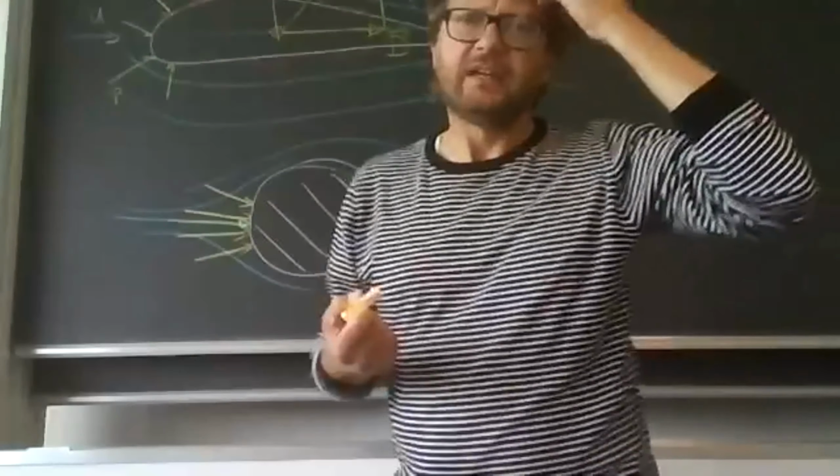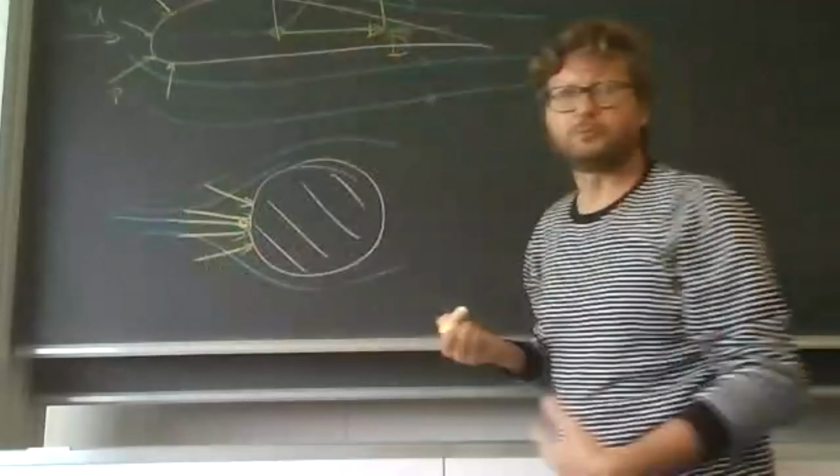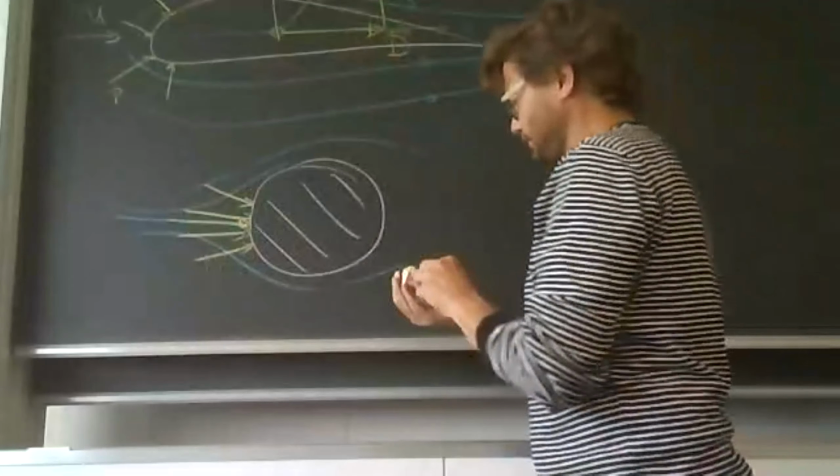And of course, on the backside, there will also be pressures. In the case of potential flow, where the flow was fully symmetric and we did not have any losses due to viscosity, the velocity field was fully symmetric, and the pressures here were of equal magnitude, just in opposite direction, right? And that's why in potential flow, the two pressures cancel each other.